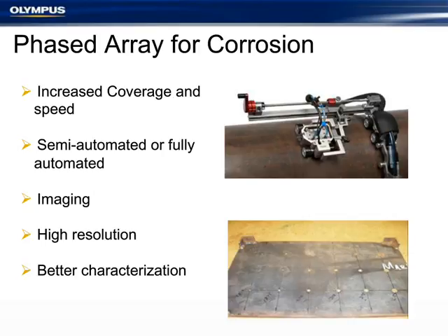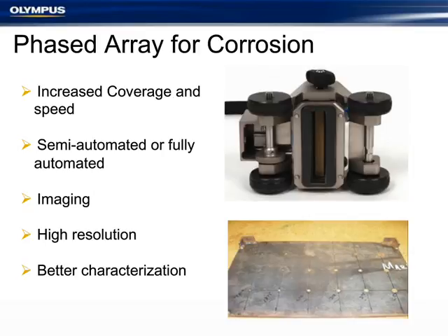But really all we're doing is, the ability with a phased array probe to generate, say, 50 to 60 beams out of a 2.5-inch probe versus a small 1-inch transducer that can only generate one. So here we have a 64-element probe. In order to improve resolution, we basically use a water wedge concept. So we're going to have better near surface resolution, especially if the surface isn't perfect. We have a sealing gasket here.